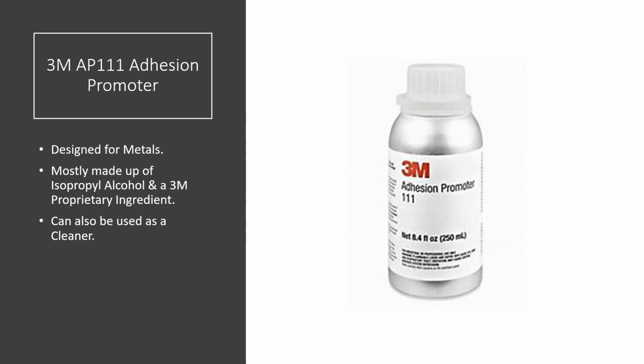AP111 was developed for metals. It's made up of mostly isopropyl alcohol and a 3M proprietary ingredient, or as 3M likes to call it, some fairy dust. This product is 99% isopropyl alcohol, but it's helped use in the cleaning process to create a desirable surface for a VHB tape, a double-coated tape, or transfer adhesive tape to stick to.